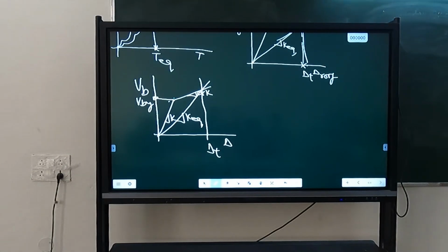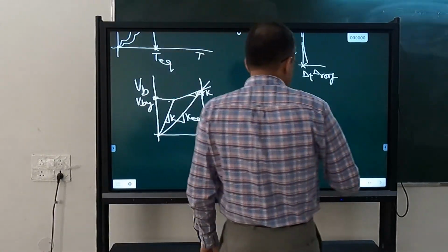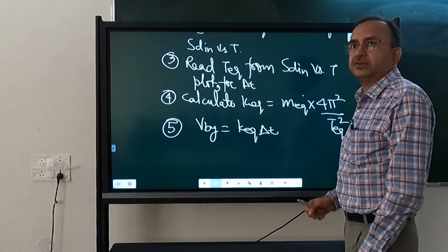Yield displacement we can calculate by the relationship between SD and delta. So initial period is same, ductility ratio is same, and the equivalent period, secant period, is also same. And then its properties are related with the multi-degree freedom system through mode.